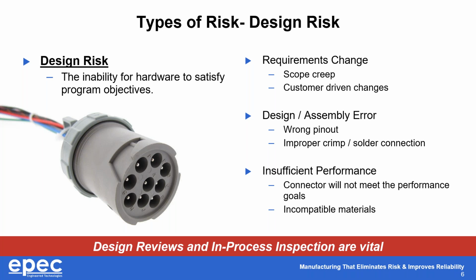Some of these are pure customer-driven changes, such as a complete change in the design, the color, a connector. All of these things manifest themselves as design risk. But other things like operator error can occur. The wrong part can be crimped. The wrong connector can be ordered, or a part number could be mixed on a design proof. All of these things happen.